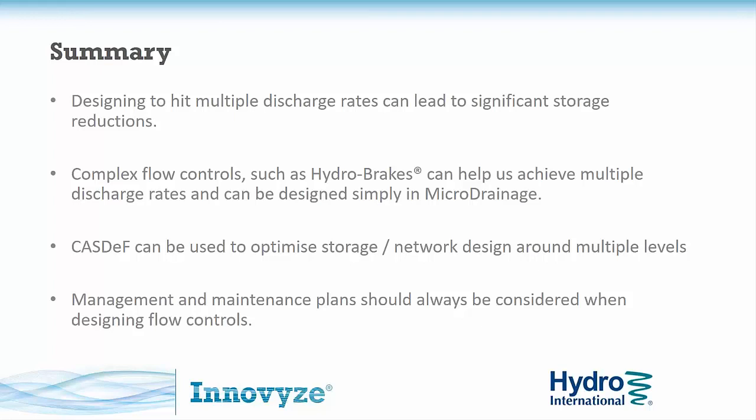It doesn't have to be so complicated. We're using that complex flow control wizard and just working on cumulative depth and flow relationships within MicroDrainage, using those hydro breaks to really help me control the flow and get that small variation in flow rate for large differences of head, which makes life a lot easier as well. I also use CASDEF as well. And one point that I'm really glad that Chris raised as well was the management and maintenance plans when we're designing these flow controls. Often very overlooked, but certainly something that, again, I know Hydro will be able to talk to you in regards to that.